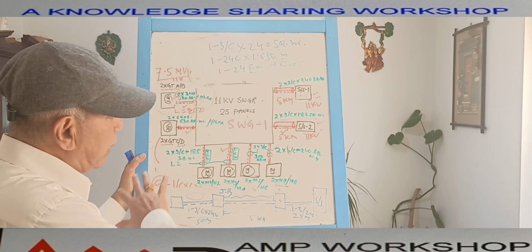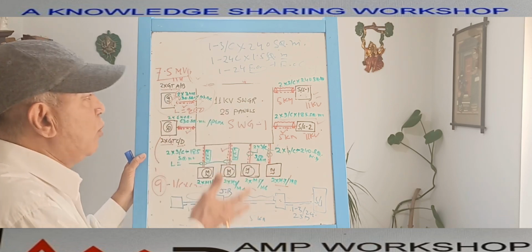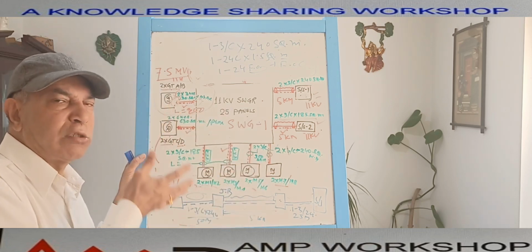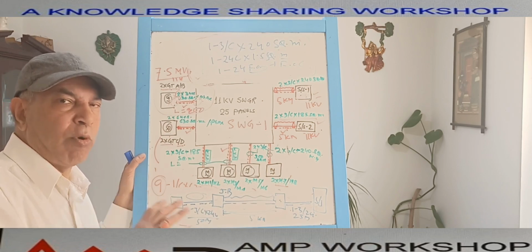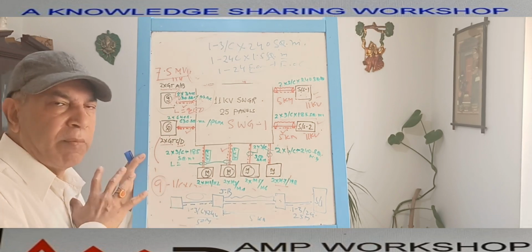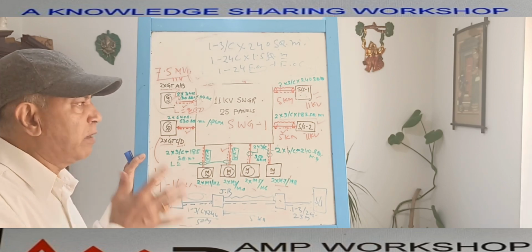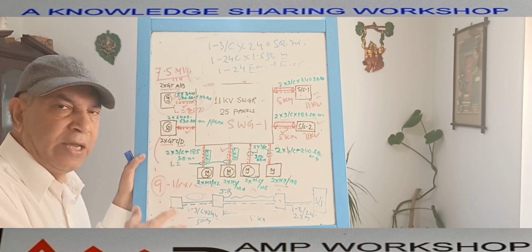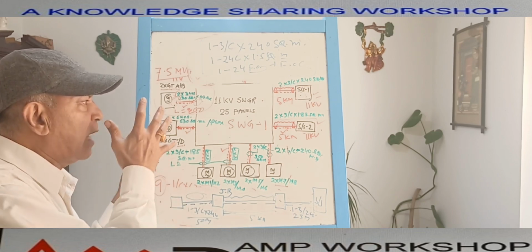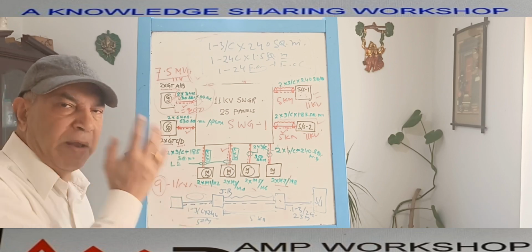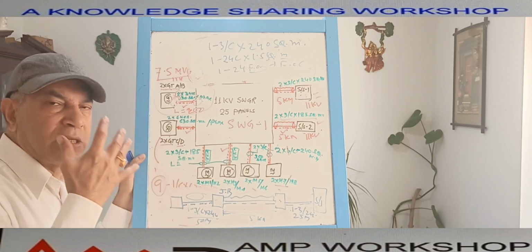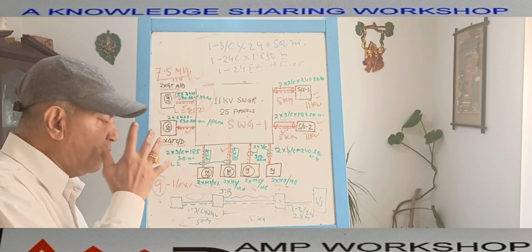This way we can develop the cable block diagram, which will be a useful tool, or useful drawing, from various points of view to understand what the various types of cable are, what the size of the cable is, what the length of the cable is, what the mode of connection is, what the mode of laying is, how many cables are coming to the switchgear, what cable entry provision is required, what the size of the gland is, and what the size of the lug is.